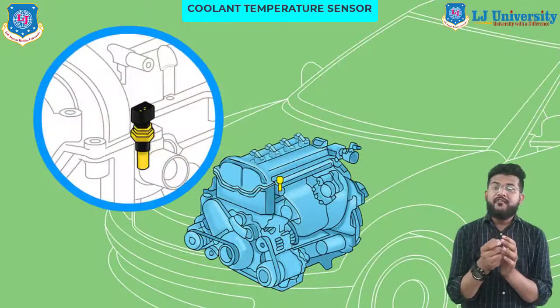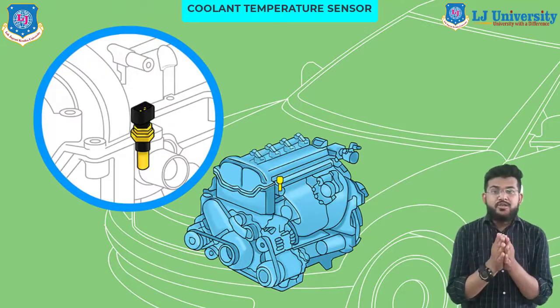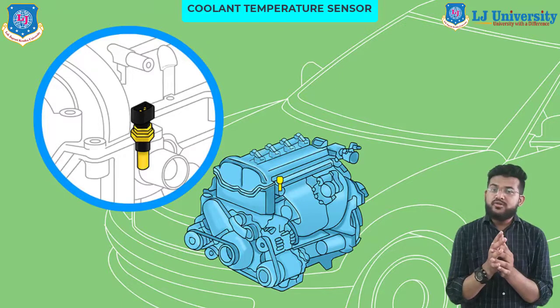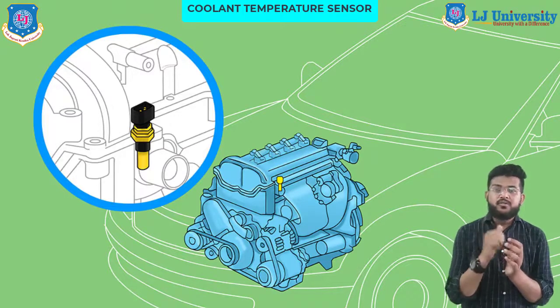Start by having a look at the unit itself to check its condition, as the sensor gasket and connectors can develop cracks with extended use, or you can say continuous temperature cycling. The coolant temperature sensor is usually found at the front of the car near the thermostat housing or on the radiator. While a visual check can help to diagnose some faults, not all the problems are associated with a CTS which is showing these symptoms.